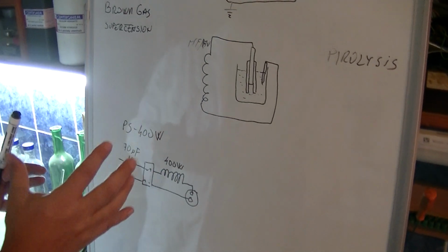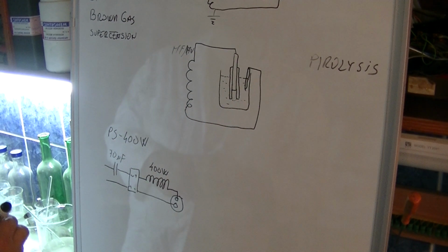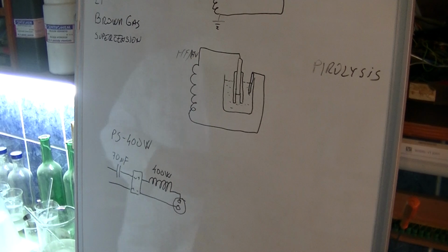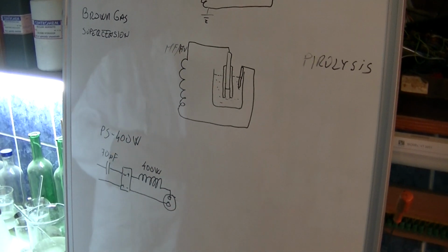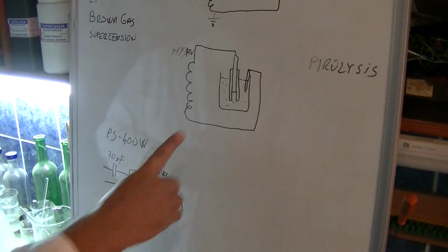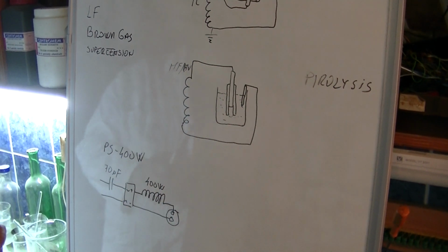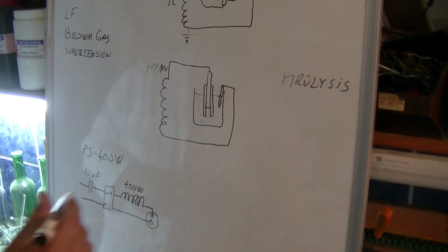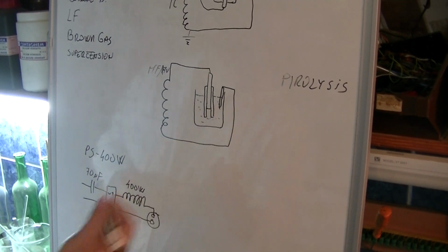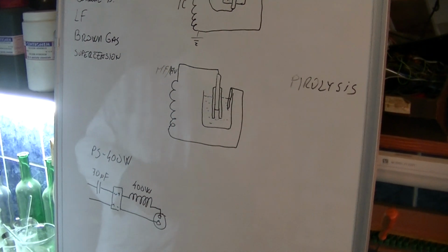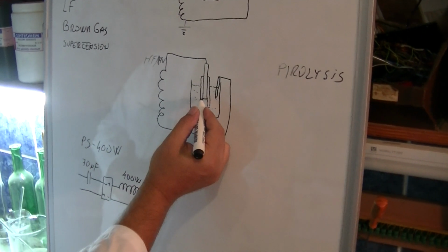But in that case we are making decomposition of organic material, which consists of so much hydrogen and oxygen in its structure, and carbon as well. So with a very low current, at the beginning we are producing a very high amount of gases, until this surface, where the gap is, is carbonized, because carbon will be left.